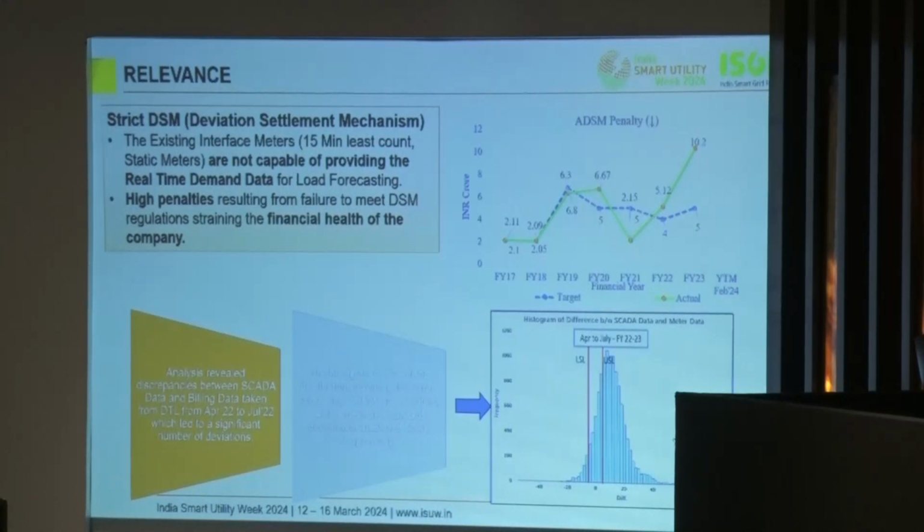And that too, after that analysis we were doing, after 1 month, when we could actually get the data from DTL. That was not being done on a real-time basis. So in this histogram at the right below, you can see the error distribution, in which errors surpass plus minus 5 megawatt, which was the desired value. The mean was 10.55 and the standard deviation was 10.94.